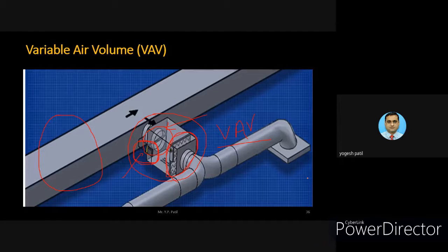This system is common in different types of offices, rooms and buildings because it is more energy efficient compared to CAV. CAV systems are not popular; constant air volume is another type of model that has been replaced by VAV. They can also allow zoning in the building. It is possible to have zoning. You can see that these particular things are divided into different zones also.